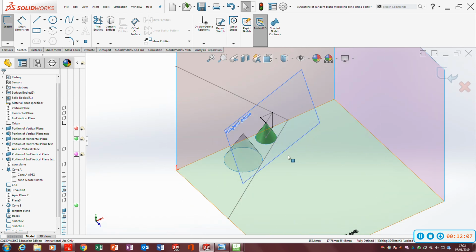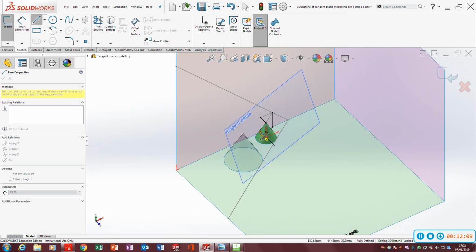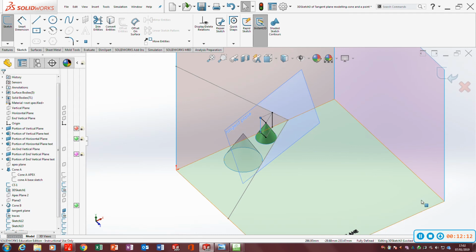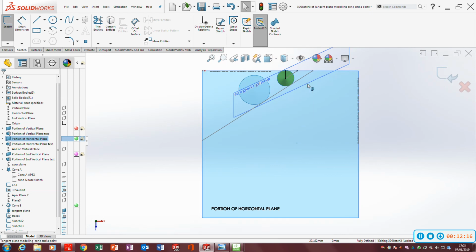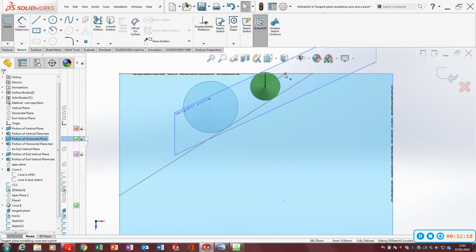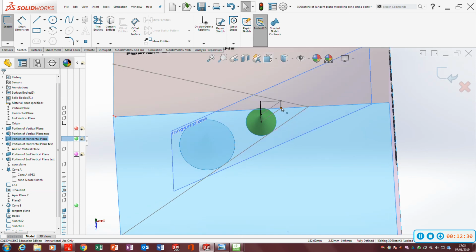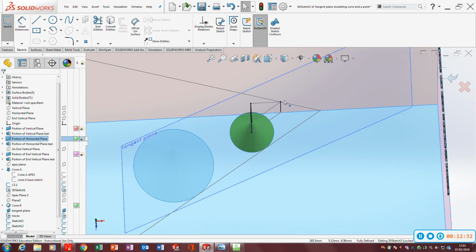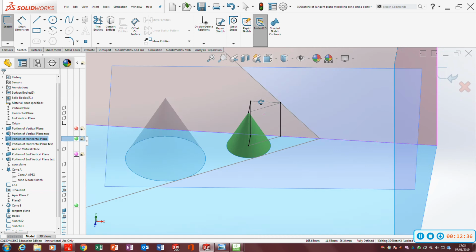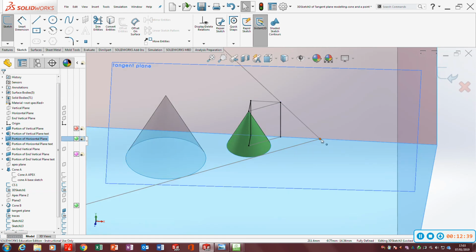So to make sense of that for you, when a line parallel to the HT hits the XY line, it's on the vertical trace in elevation, provided that the line you're drawing is on this tangent plane. So that line there, it hits the XY line in plan, so its point there is on the VT in elevation. And if you have 2 points, you can define lines.